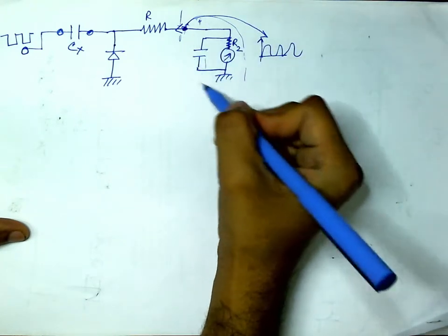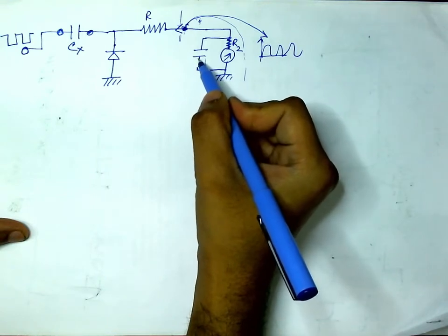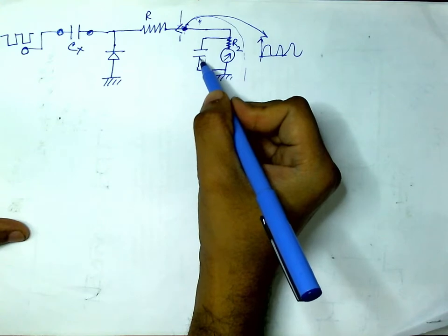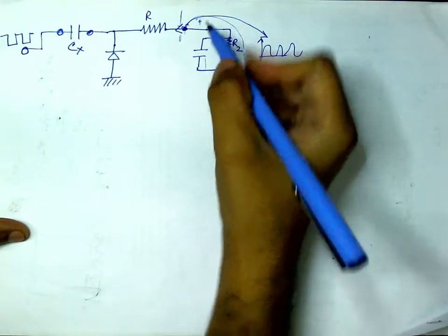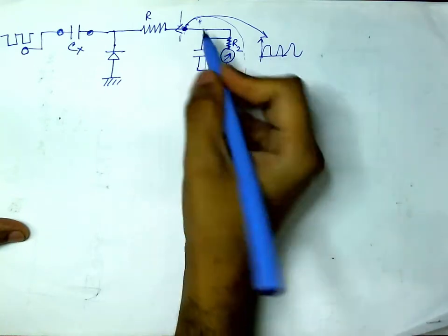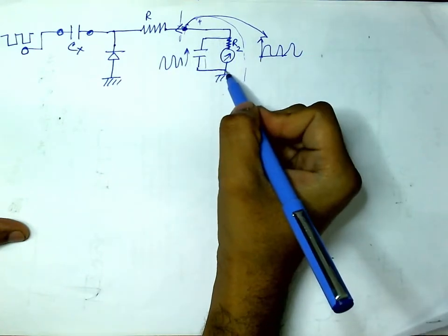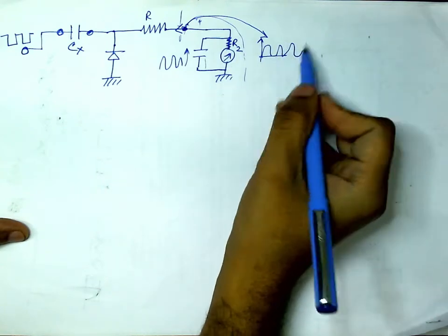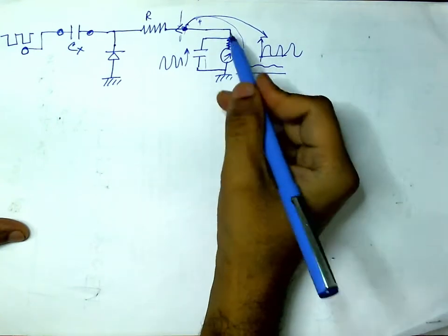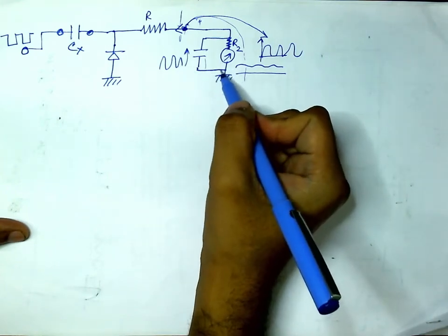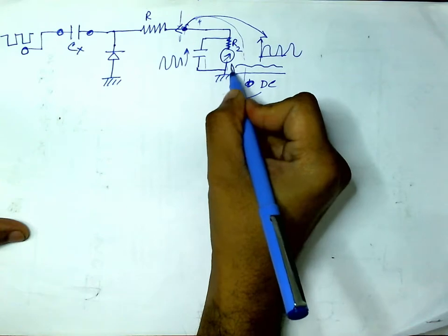So the current here will also be oscillating, but capacitors are low resistance to high frequency oscillations compared to resistance. Therefore most of the oscillating AC part will go through the capacitor, and if you do a harmonic analysis of this current, only the low frequency part and the average value, pure DC, will go through the meter.